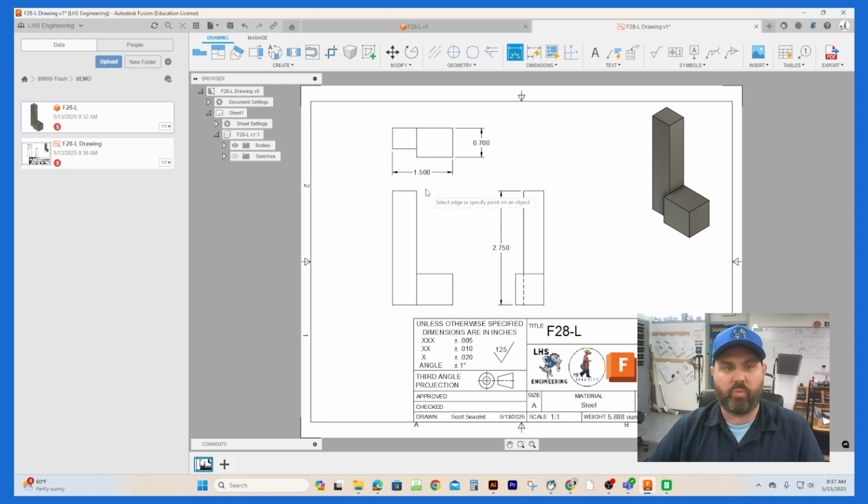Next we need to determine that it is fully dimensioned. So there's more numbers. We don't know how thick this part is over here. We don't know how wide this is here. So there's a very simple method to moving around a drawing and figuring out if it's fully dimensioned. One thing to remember is any dimension up and down is shared between these two views. Any dimension left or right is shared between these two views. And any up and down dimension on the top view is shared with a left or right on the right side view.